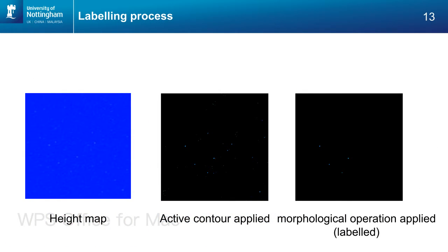As previously mentioned, aside from the classification neural network, segmentation neural networks can also be utilized in our research and demonstrate the defects explicitly. UNet, as a newly developed segmentation neural network, is effective for showcasing morphologies of defects. Samples made of another nominated material, maraging steel, were measured under focus variation.